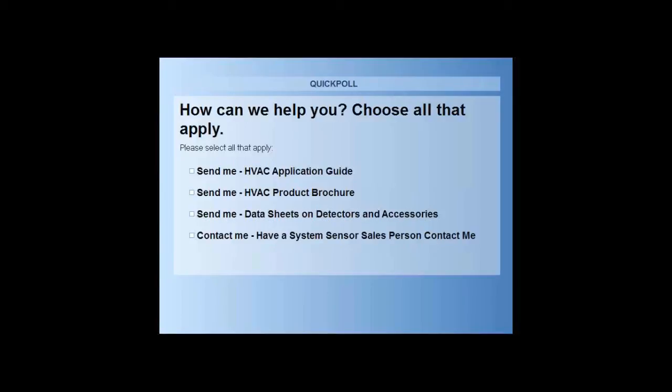Let's see, question number 7. 606.2.2. Duct detectors are not required in individual power fan units, but is... does that also mean that VAVs must shut down if they do not have an individual duct detector? That refers to common area returns or open air. So each individual unit in the entire area, all units shut down on detection. So 606.2.2 would be an example where there is limited global shutdown.